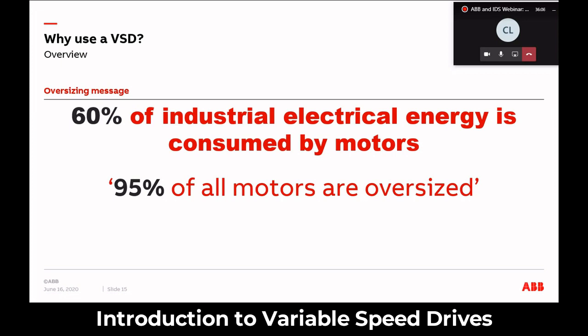Or it could be from a sizing perspective, where they've got an absorbed power of say 100 kilowatts, but they haven't got 100 kilowatt motors, so they may go to the next standardized motor power, which in this case would be 110 kilowatts for a standard induction motor. But hypothetically, it could be a lot larger than that, depending on the type that they're using.